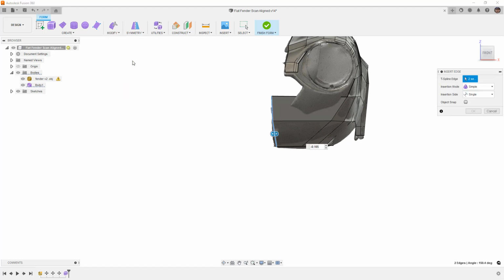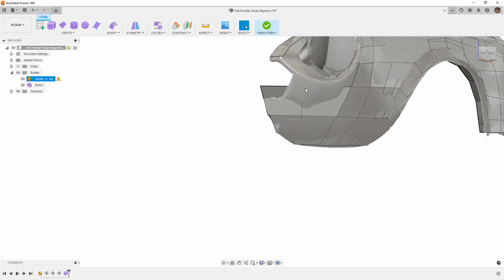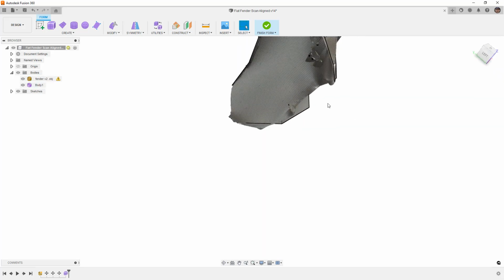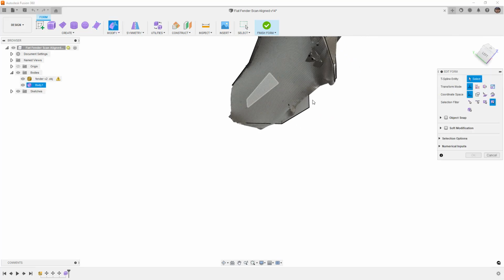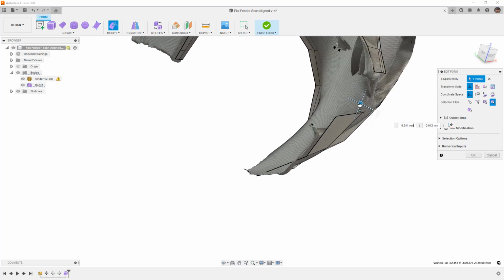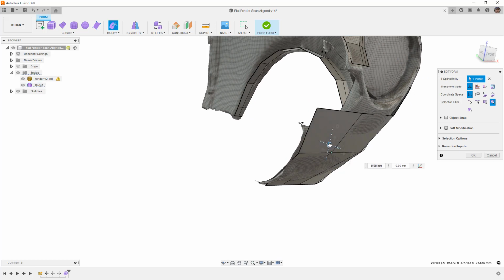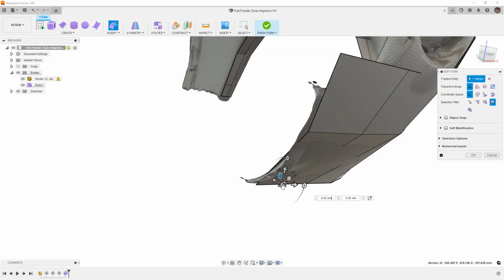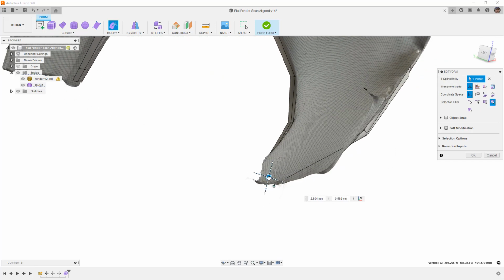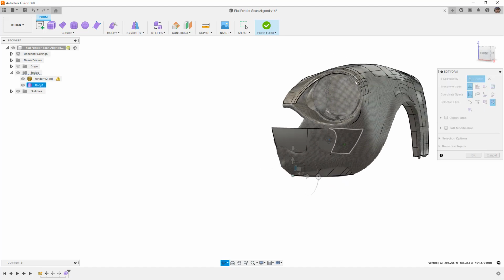So I'm going to double click there, insert edge, I'm going to do 0.5 right in the middle, and then pull it out. So we're going to start pulling it out with that vertex in there. So modify, edit form, find that vertex, pull it forward. Again, we don't want it flat, so even if this is relatively close, we're going to pull these forward a little bit. Or we could potentially pull that one back and double check smooth display.